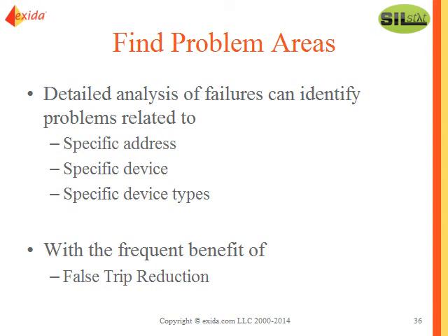So you may have 100 particular transmitters in your site. You may find issues with a particular transmitter and decide, hey, from now on we should switch to a new technology or a different manufacturer and so on. So those are items that you can look for while you are recording data. That should help in reducing false trips. So in the end, your compliance attempts with the standard lead to better data. Better data will lead to better design of your plant, with reduction of false trips and better operational experience. So in the end, it makes your plant simply better.